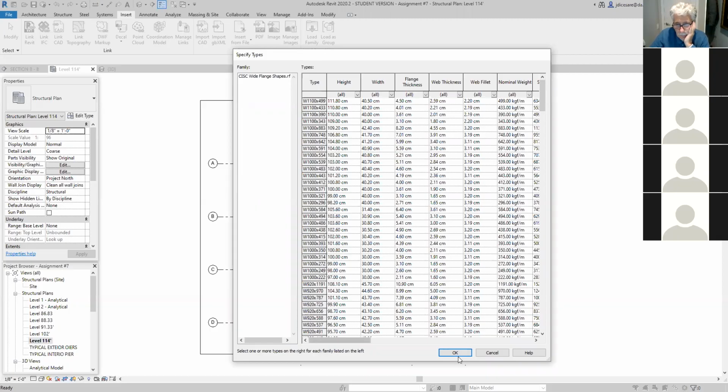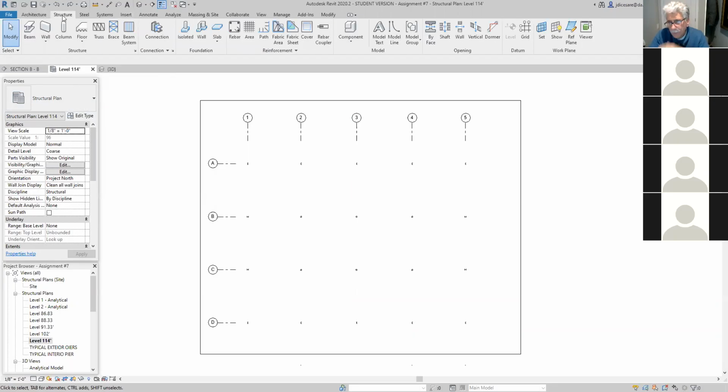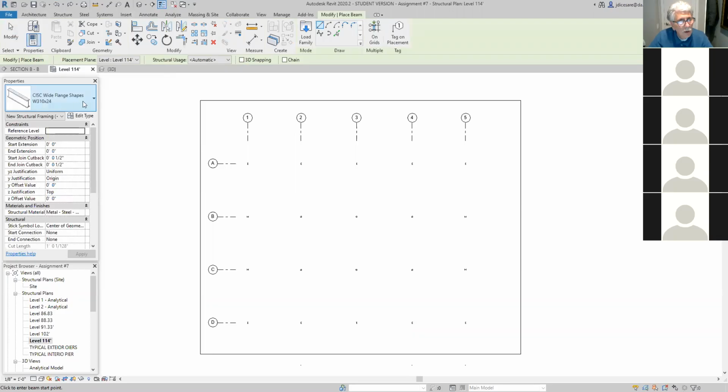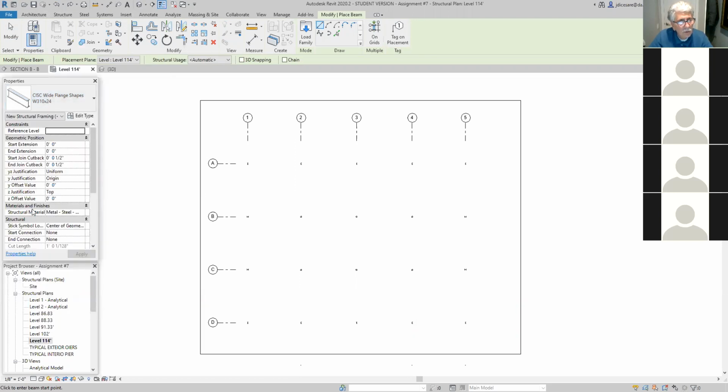Okay, so now, Johara, you've loaded your family, so you're on the Structures tab. Johara, Structures tab, is that good? Okay. So go to Beams and fly out your menu. Go where you have your steel beams, CSI, and go get a W310 by 24. Click on that. Okay, that's what you should see up here.